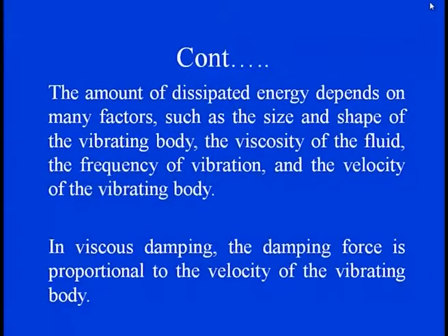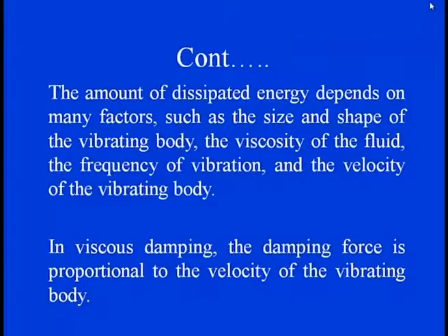Third is the frequency, the number of cycles per unit time. And second, the velocity, or the amplitude of the velocity, of the vibrating body. In viscous damping, since the damping force is a function of the velocity, we need to check what exactly the velocity of the vibrating body is.